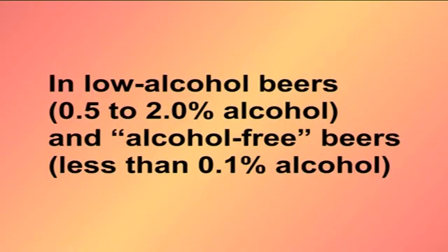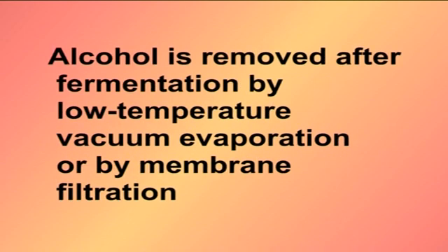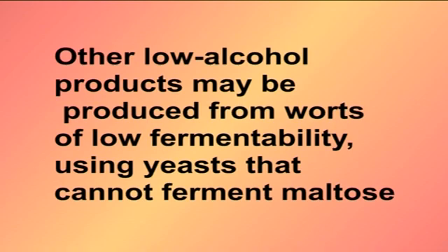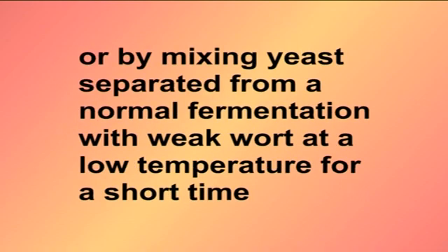In low alcohol beers, that is 0.5 to 2% alcohol, and alcohol free beers, less than 0.1% alcohol, alcohol is removed after fermentation by low temperature vacuum evaporation or by membrane filtration. Other low alcohol products may be produced from worts of low fermentability using yeast that cannot ferment maltose or by mixing yeast separated from a normal fermentation with weak wort at a low temperature for a short time.